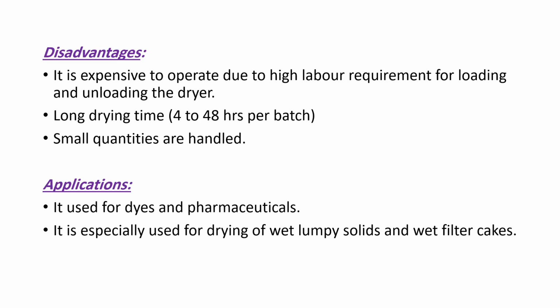And the disadvantages are it requires high labor and long drying time, because it can take about 4 to 48 hours per batch, so it can take 2 days, which is so long. Then it has small capacity because it holds only small quantities. Then the applications of tray dryers: it is used for pharmaceuticals, dyes, wet lumpy solids, wet filter cakes.